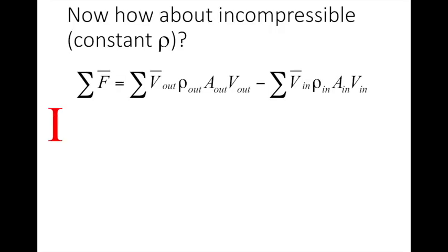Now for our incompressible assumption, we discussed on Monday that we need to be careful with this one. It doesn't help us out all that much in and of itself, because our tendency is to get rid of the density like we did with the continuity equation. But unlike the continuity equation, where we set the entire relationship equal to 0, with the momentum equation we're setting it equal to the sum of the forces, meaning we also would need to divide those forces by our density, which only makes our life harder. That doesn't really get us anywhere.